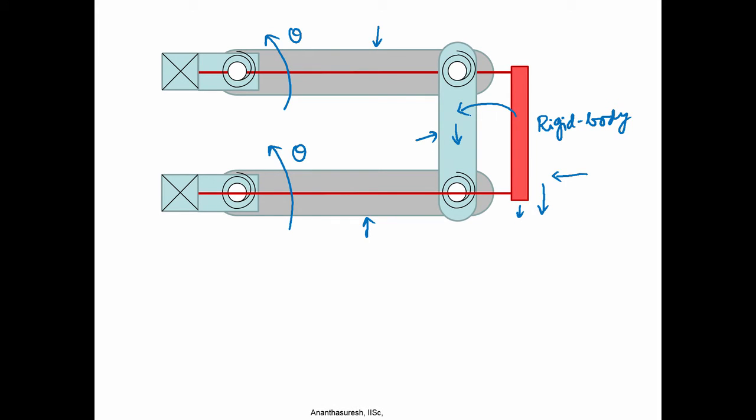and there are torsion springs at all 4 of them, and if you put the values that we have indicated, then the behavior of the pseudo rigid body model will be very close to that of the elastic body one if you were to do finite element analysis and compare. That is what we want to do and see for ourselves, that this is a good model to approximate the large displacement, that is nonlinear behavior, of a compliant mechanism comprising slender beams.